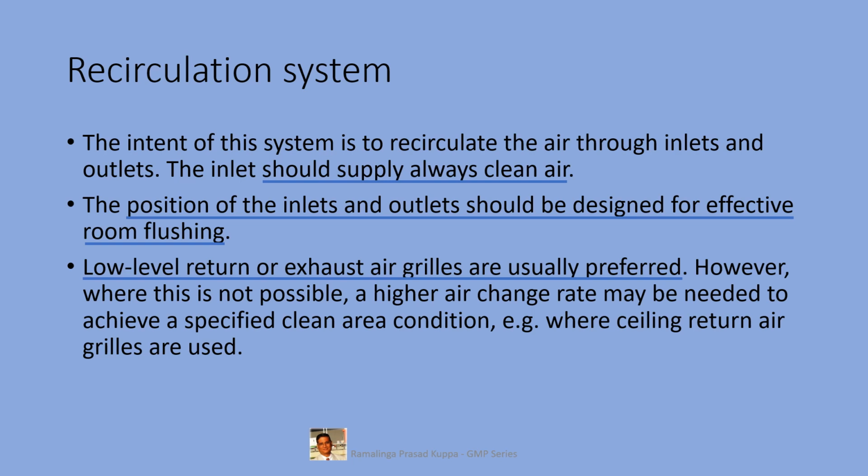However, where this is not possible, a higher air change rate may be needed to achieve a specified clean room area condition, for example, where ceiling return air grills are used. If there is adequate provision, it is always preferable to have the return air outlets at lower levels. If the return air duct is located at higher levels, you may have to go for higher air changes.